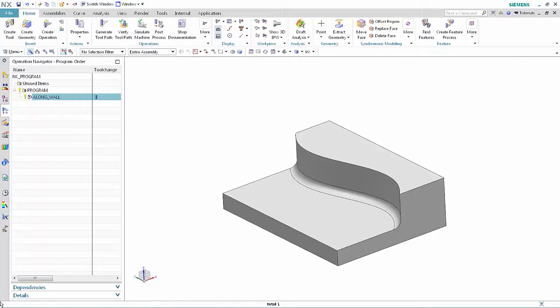This concludes the demonstration of how you can now specify either a U or V control direction and ignore system-defined vectors, allowing you to interpolate the tool axis for variable axis operations along U or V ISO curves with as little as a single interpolation vector for each curve.